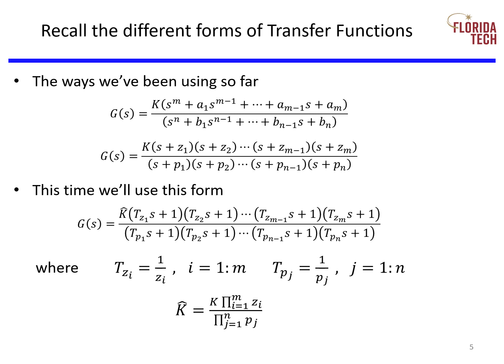By factoring out all the z's and p's, we know we no longer have coefficients of 1 in front of each s. The new coefficients are either 1 over the specific z factored out or 1 over the specific p factored out. We know that 1 over z, or 1 over p, is defined as the time constant, at least for factors resulting in a real root. Therefore, we'll choose to treat the new coefficients of s as time constants and define them using capital T's with a numbered script of either z or p, depending on whether it's a numerator or denominator factor.